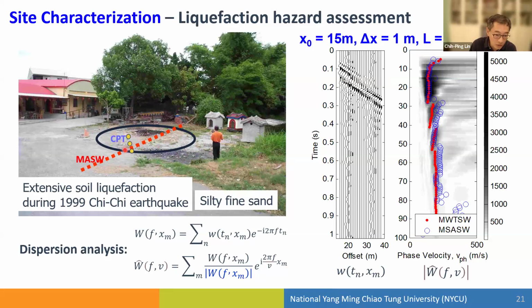We initially had just 12 meters. We wanted to restrict the survey to the same area, but if you have a short array, you couldn't distinguish the higher modes. You couldn't separate the fundamental mode from the higher modes. So we had to settle for a longer receiver array. And back then, with the commercial software, we could only use the fundamental mode inversion, right?